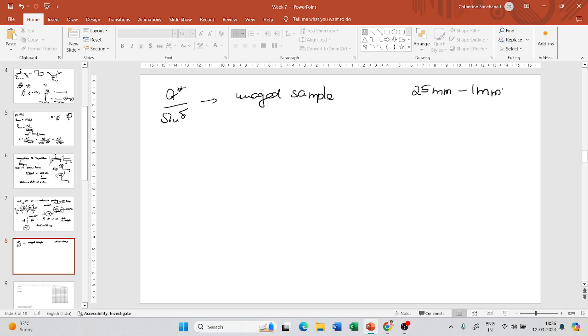You will be subjecting the bitumen to a few high temperatures and finding out the PG high temperature of the bitumen. You will do this on two types of samples: one is an unaged sample and one is an RTFO aged sample. Now let us see the case of the unaged sample.